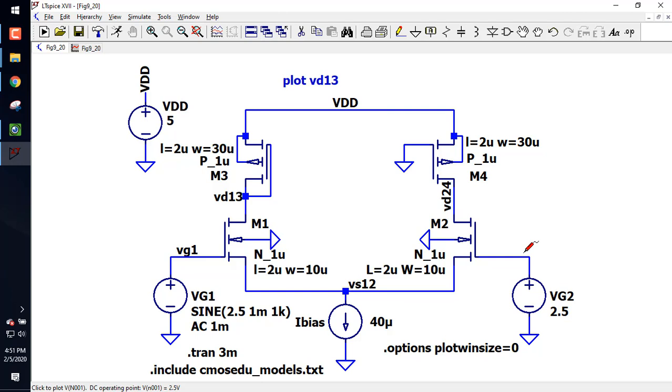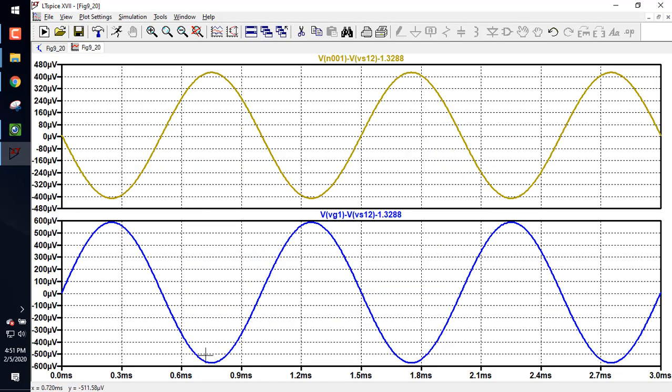Does everybody see that when this voltage goes up, this voltage goes up, this voltage does not change? So here I get a VGS that's positive when the input's going up, and here I get a VGS that's negative because this voltage goes up and this stays the same. Now what happens when the input goes down? When the input goes down, the VGS of M1 goes down and the VGS of M2 goes up. Everybody follow that? So you see how they're out of phase? And then you say, oh, VGS1, the blue, is equal and opposite to VGS2. Any questions?